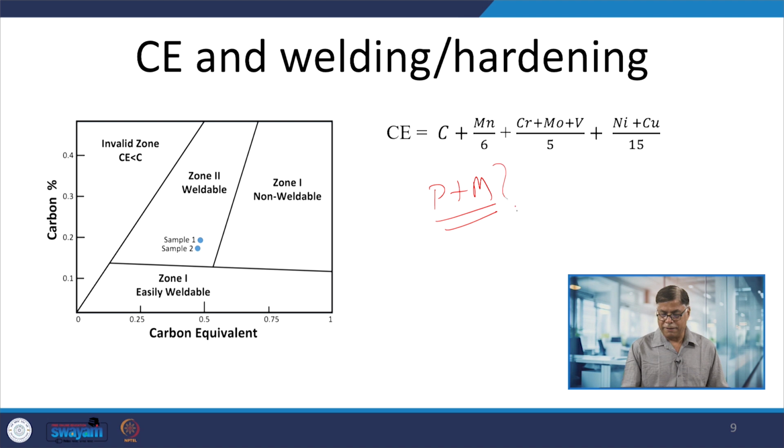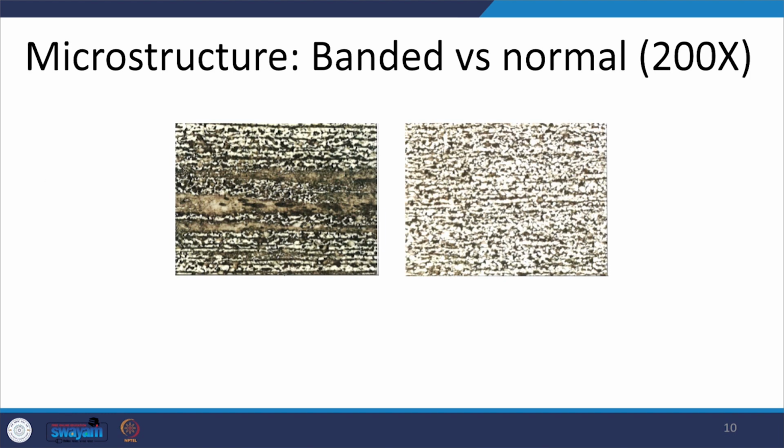Okay. So, the thermal cut steel plates, when subjected to deformation to roll down into the shape of pipes, will certainly make the job of deformation difficult first and increase the tendency of cracking. When the steel was analyzed for microstructure, it showed a lot of banded structures, and these banded structures are known to show greater notch sensitivity for cracking as compared to the equiaxed structure. So, the normal versus banded structure.